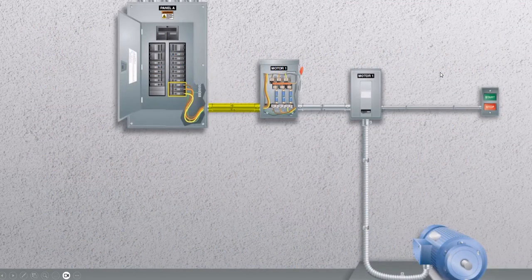The big thing to remember about motors, and I think I probably did this in my presentation, I can't remember if I did or not: when you're calculating this, you're going to use 125%. This is for short circuit and ground fault protection, overcurrent protection, and sizing conductors. You size them from the NEC. The FLC comes from the NEC. If you're sizing overloads, that is going to come from the nameplate rating. You do not go to the motor and look at the nameplate rating and go, 20 amps, and then size your overcurrent protection based on that. That would be incorrect.